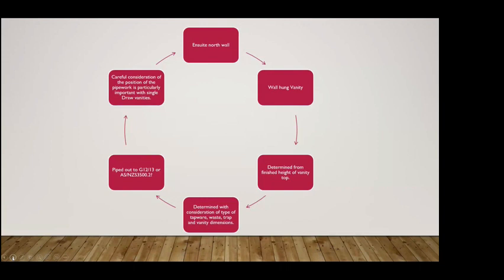You might do 5 in the morning by smoko, all sweet, all silicone, all finished, and then you get one that takes you from smoko all the way to lunch, because every time you put it on, it starts leaking. It's because one measurement's 5 mil off or something. Something's fractionally out of sync, and it's putting stress on the flush pipe, and that's causing it to leak.